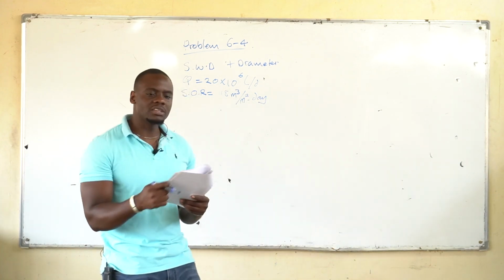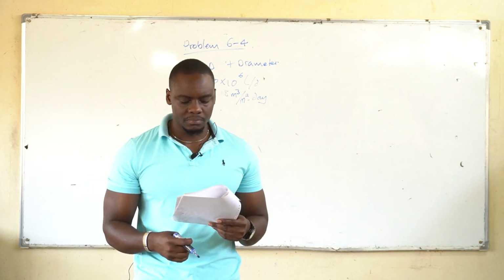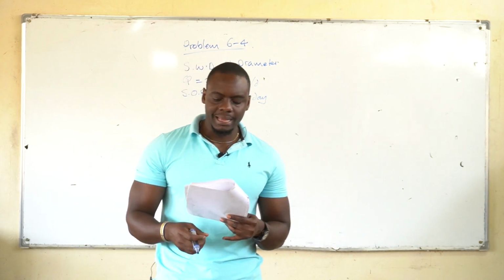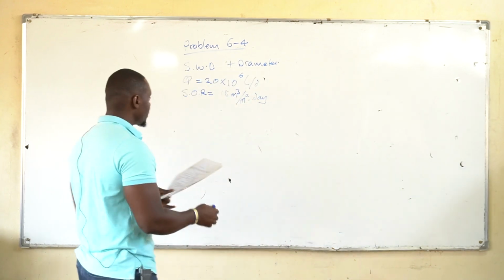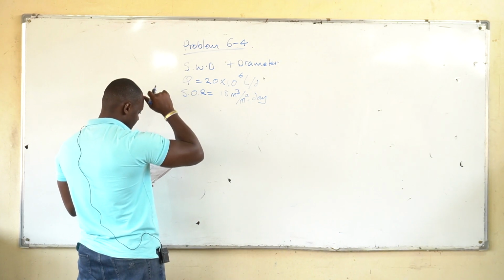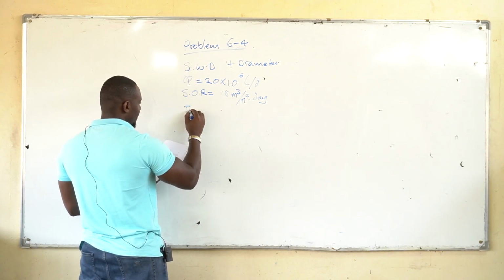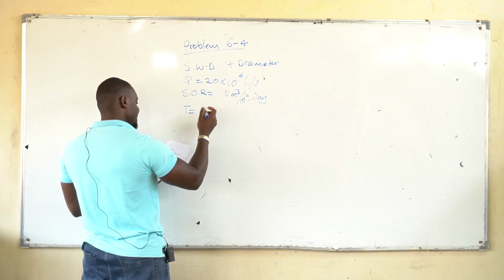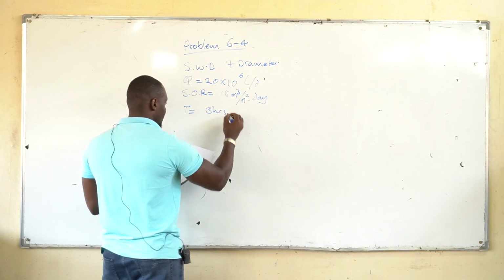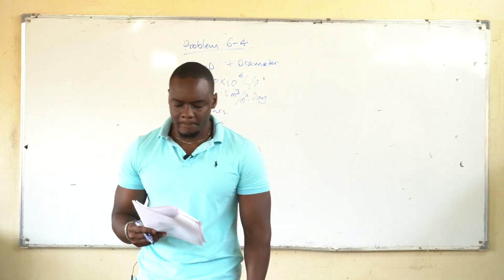The maximum SOR is 18 cubic meters per square meter per day, and the detention period, denoted as T, is 3 hours. Okay?